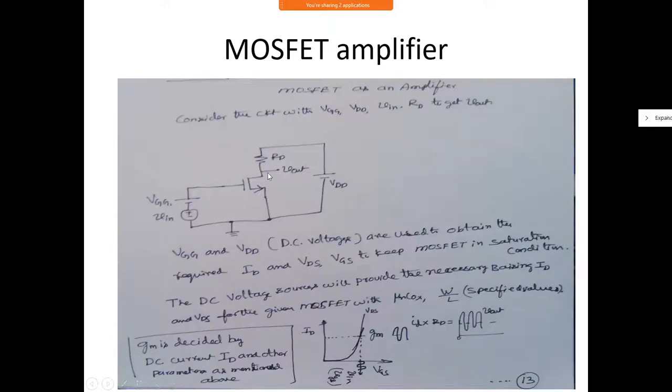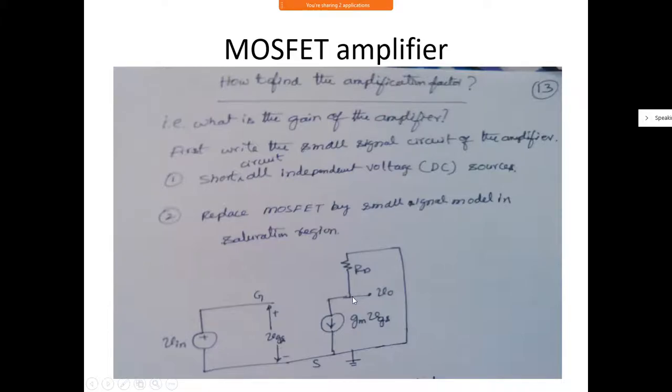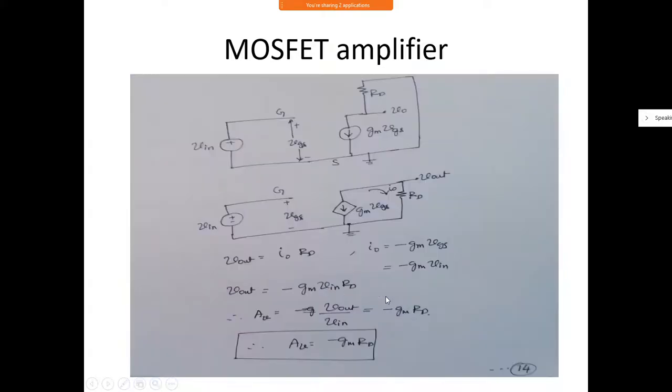Okay, let me go to the amplifier. Are you measuring the output voltage here? Is it the drain point? Is this the drain here? This is gate, source, drain. This is drain again. So this is Vout, correct? Is this still Vout? Can you see it's the same drain point? Now, when I say Vout, it is the voltage at this point with respect to ground.